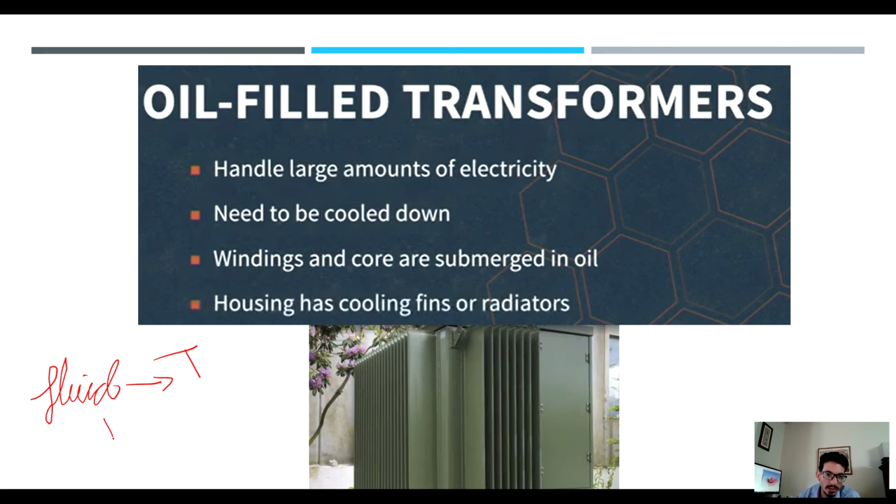This fluid has to be non-polar, because if the fluid is polar, kind of like water, you can create a pretty nasty electrical hazard because the coils are carrying high voltage, high current, or basically carrying electricity. So the non-polar fluid will not interact with the electric field, but it would help cooling the windings.